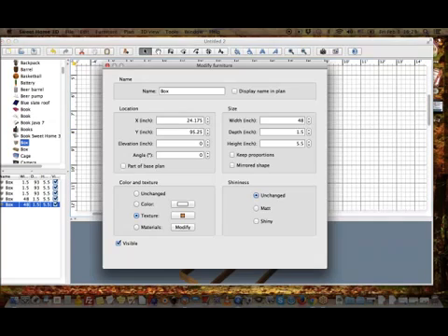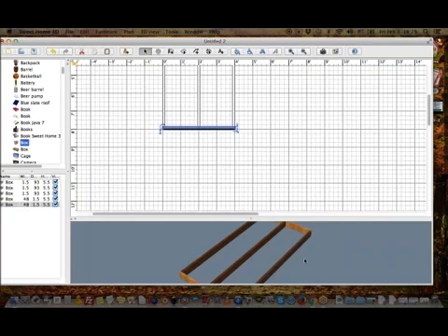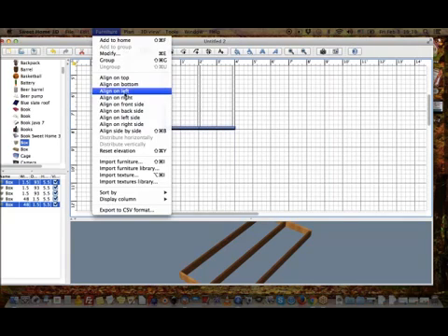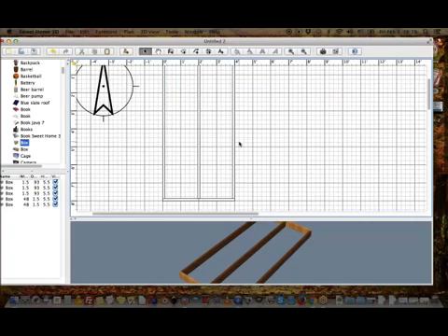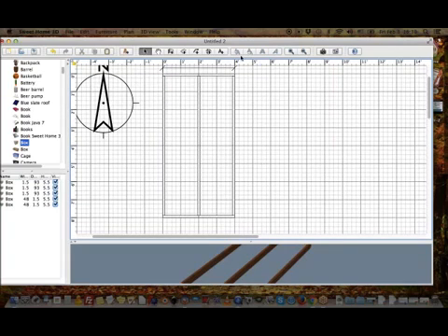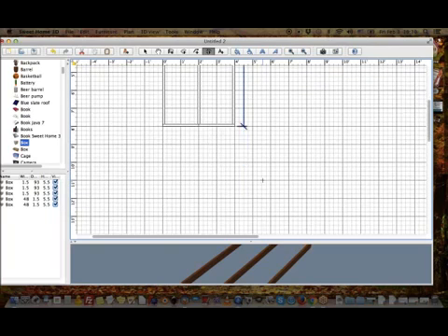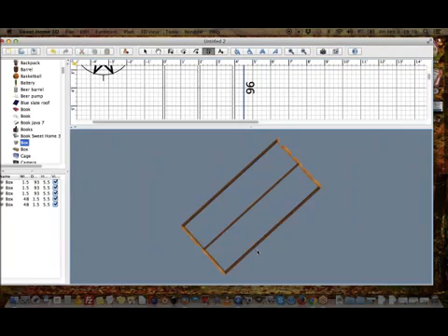So now I have two options. One is to go over here and tell it to go to X24, or I could start by selecting this one on the left, selecting the one that I want to align, and do furniture align on left. So now it aligned this corner, meaning I know this is all going to be good. Okay, so now if I take my measuring tape again here and I measure from this point to this point, I should get 96 inches, and here it is. So those are the final measurements of my module. Okay, and you can see it right here.